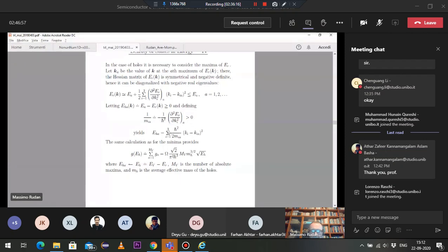Because the three coefficients are equal. And in gallium arsenide, the sphere is placed in the origin because Km is 0 because we are in the gamma point, okay? So a surface of equal energy in the conduction band of gallium arsenide is a sphere.